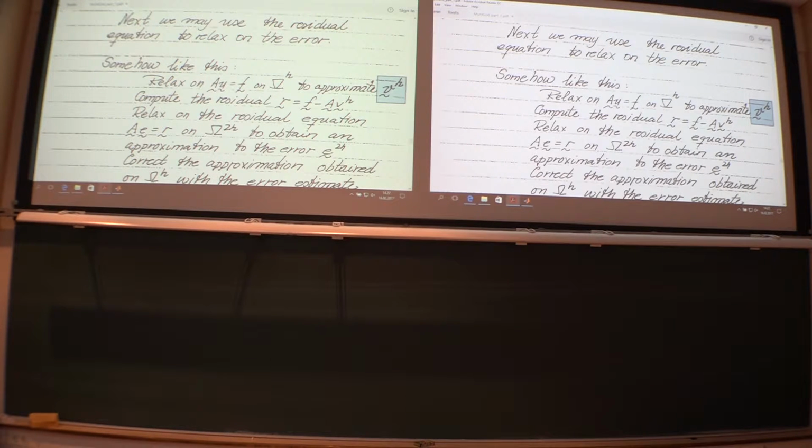Calculate the residual on the fine mesh, and then we have to transfer somehow that residual onto an equation system on a coarser mesh down here. So that r there is going to be the residual that we had, but now represented on a coarser mesh. And then we have the error which we are seeking. We guess initially 0, and then we do a couple of iterations on this equation, finding an expression for the error.